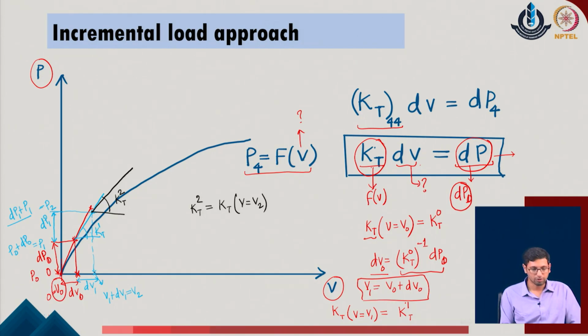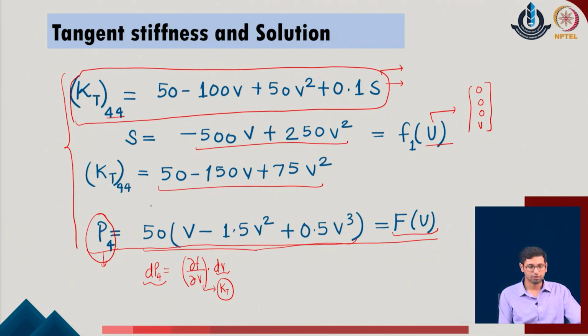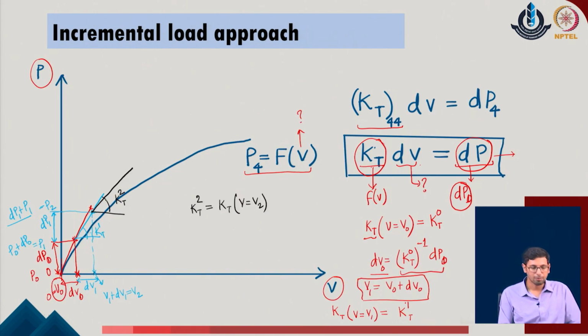So, as we calculate the individual displacements corresponding to these displacement values, I can keep on evaluating the respective value of the kT parameter of the given system, and as I am doing this evaluation, I am able to draw a new tangent line on the given system. So, this procedure can be followed to evaluate the continuously defined new tangents on the given system.